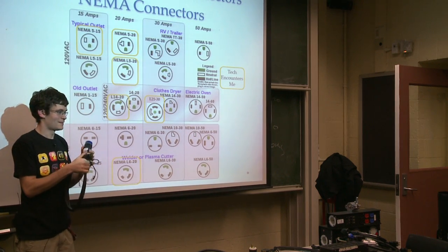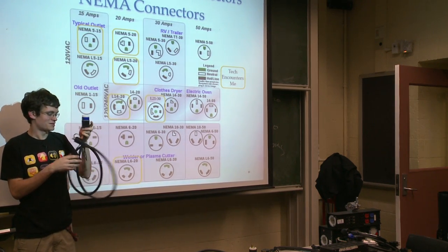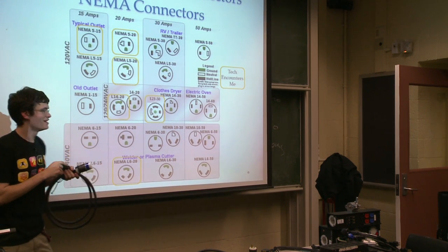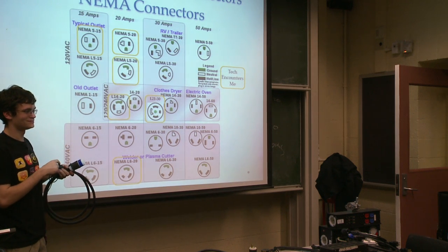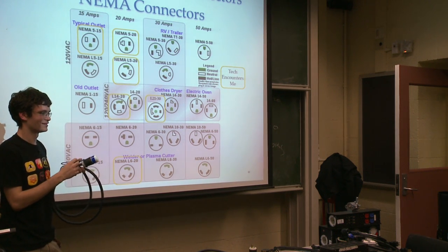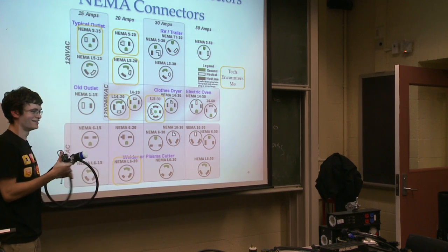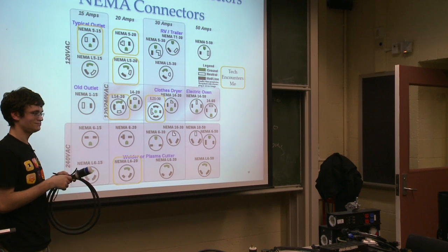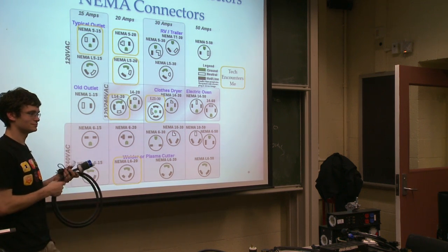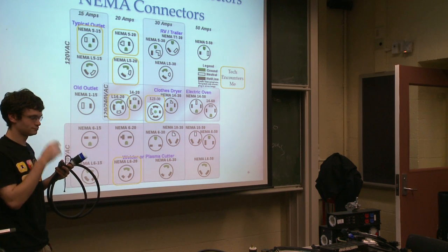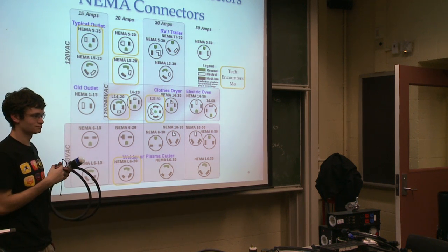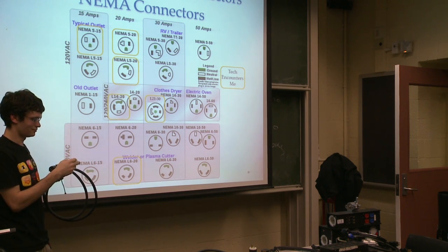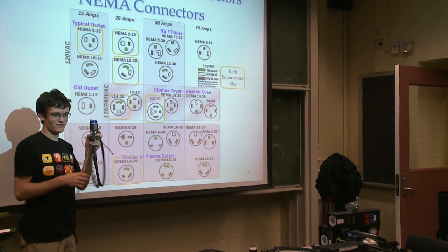Yeah. We have a specific setting. Yes, we're going from 1 hot to 2 hot. You may notice something. So, I'd like to point out that that's a very special cable, because it's for the MLs, which will accept both 208 or 120. If you're sending 120, then one of those hots on the 620 plug is actually neutral. However, if you try to plug a VL3500 into those, the thing will not last. So, yes, this is a very special cheater.